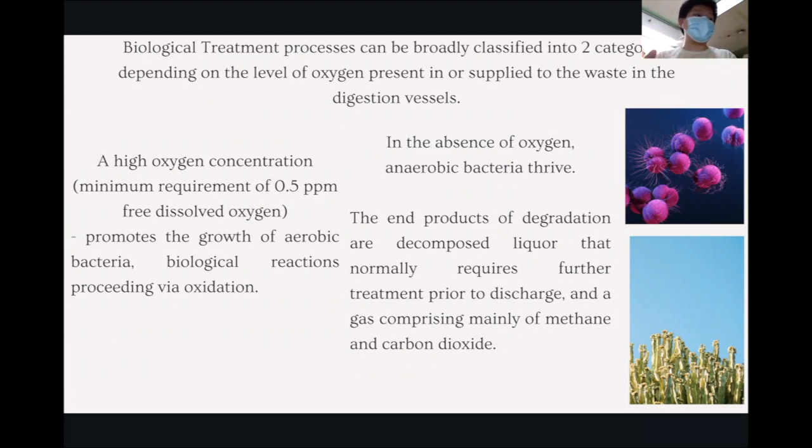The energy necessary for respiration and for the synthesis of new cells is also generated by oxidation of carbonaceous cellular materials. And in the absence of oxygen, anaerobic bacteria thrive. The end products of degradation are decomposed liquor that normally requires further treatment prior to discharge, and a gas comprising mainly methane and carbon dioxide.